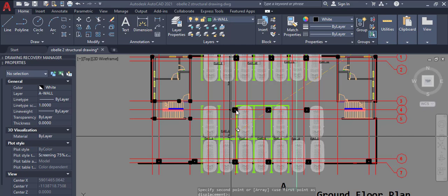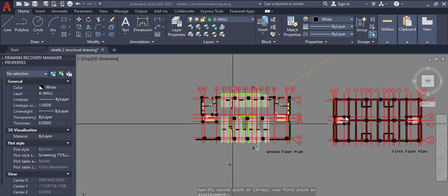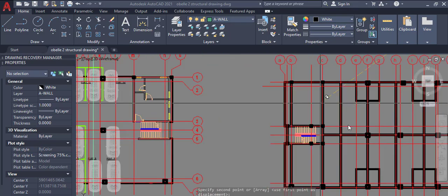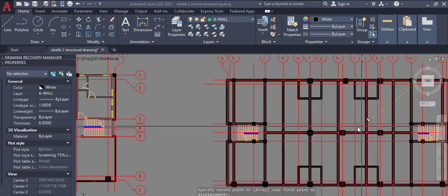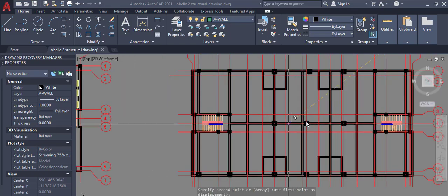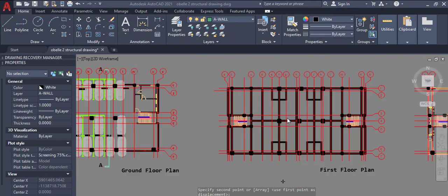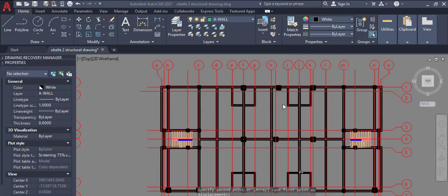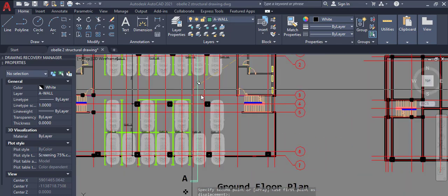And most times it may be very large because of your span, 7 meter by 7 meter. If we do it that way, all this will be a secondary beam on the primary beam, which will make it very heavy.